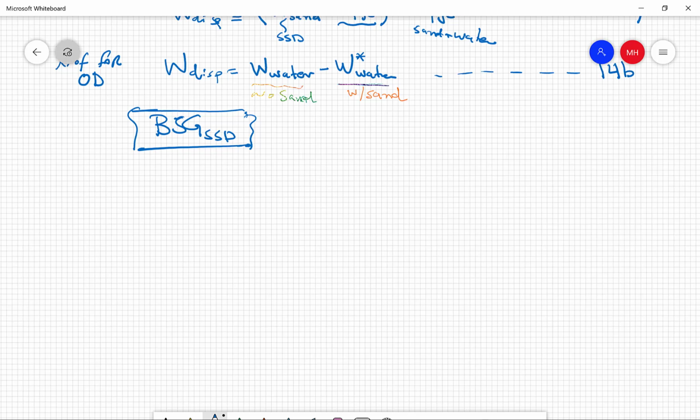Okay, to calculate now the apparent specific gravity, basically using equation 10 above, the weight of the aggregate is again the oven dry weight, and the weight of the water displaced, solid only, is the weight of the water displaced by the SSD aggregate minus the weight of the water in the pores.